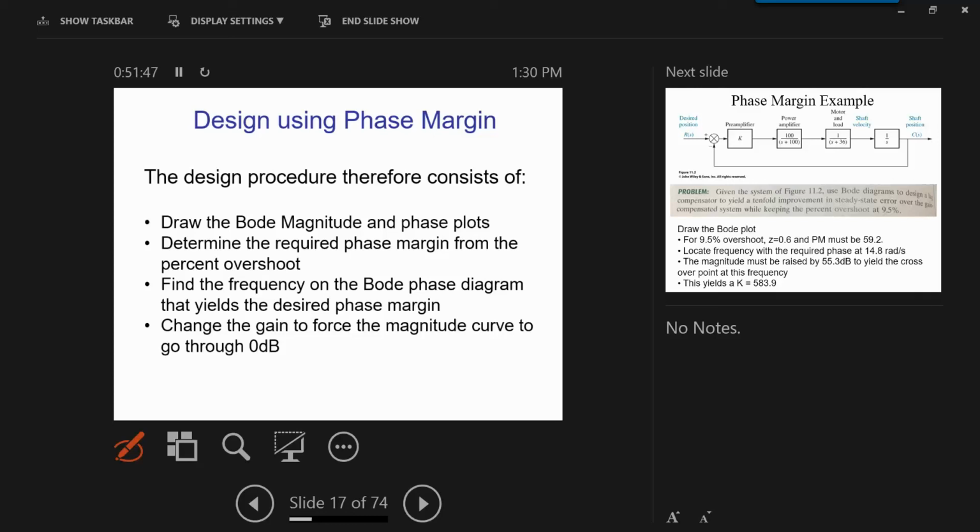So we would like to have the damping ratio always reasonable, something where the system will not have too much overshoot, and also it won't waste a lot of energy. So this is what we want. In all control systems you look at, the damping is most of the time between 0.6 and 0.7. It depends on the application.